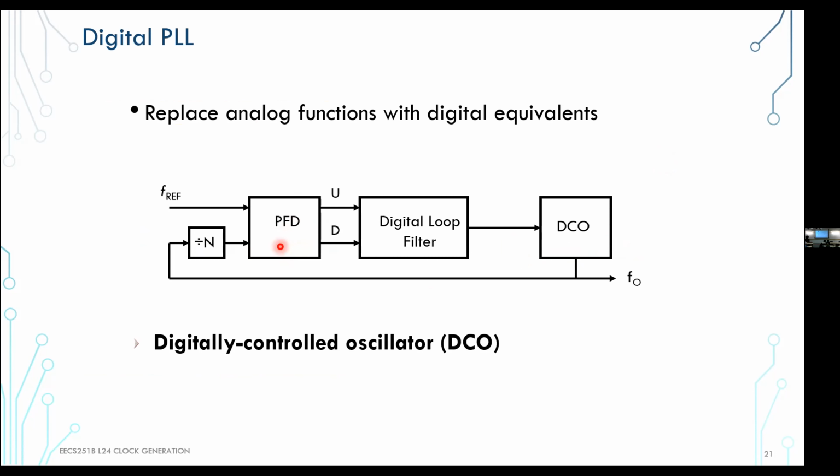So what we're going to do is try to design a loop where we have some phase frequency detector, we're going to talk about it, that gives us directly digital information here. Then we have a digital loop filter, which, by the way, is in the modern technologies a lot smaller and more compact than the previous things that I've shown you. Because remember, in the charge pump, to have small ripple at the output charge pump, I have to have a huge capacitor, potentially. And in addition to that, something that we didn't really talk about in the previous noise analysis, remember that R, that zero resistor, has some noise.